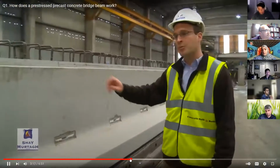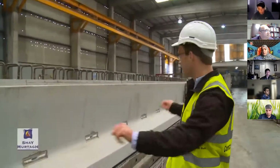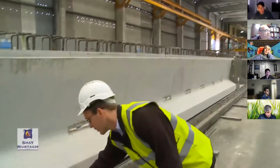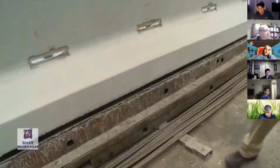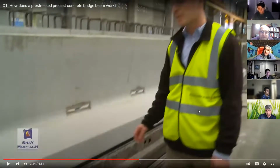Beam is one of our finished products. This was actually cast not long ago on this bed itself. Now, you'll notice there's a bit of a gap between the soffit of the beam and the actual bed itself. Why is this gap? Is the beam deflected upward? Yeah, it is cambered, right? It is pushing itself up.